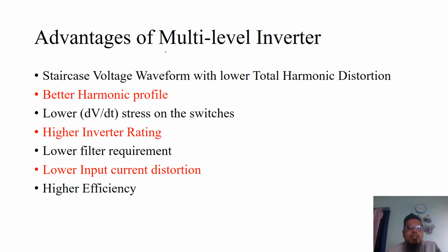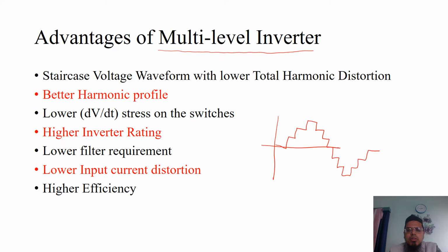While in case of multi-level inverter, we have got a staircase type of waveform in the output voltage, which resembles closely a sinusoidal wave. The more number of levels, the more this waveform is close to a sinusoidal wave, isn't it?